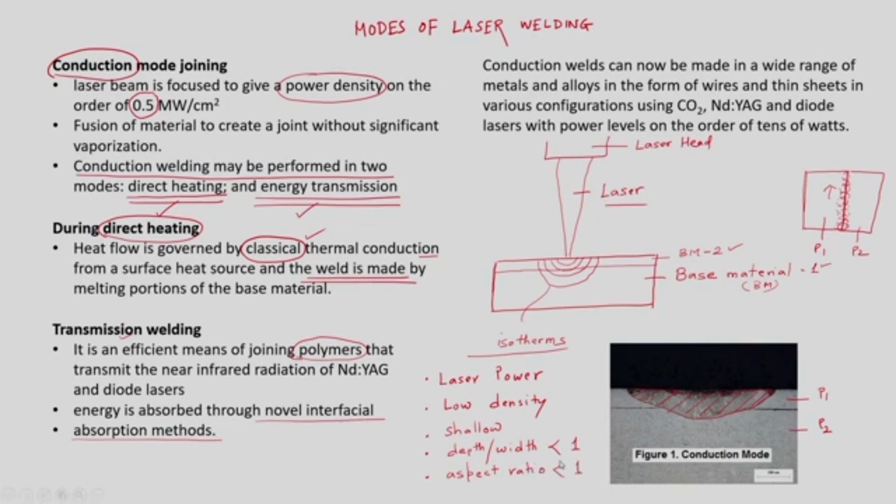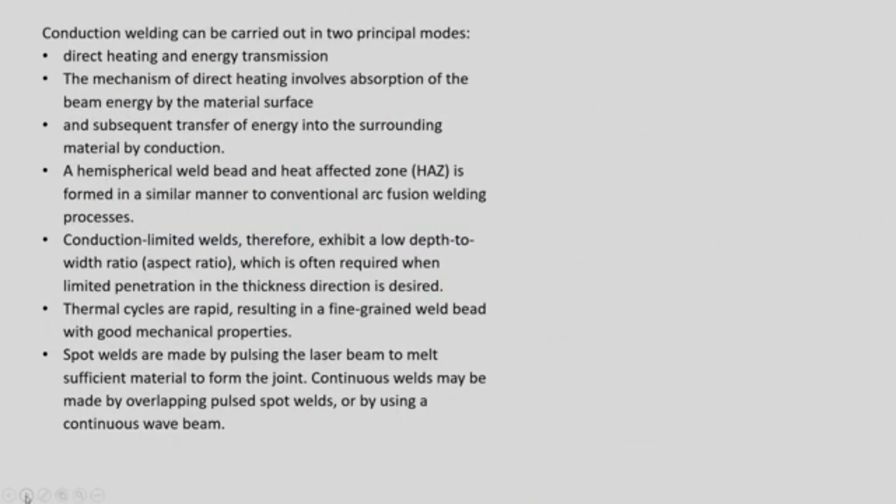So in conduction mode in particular, we are getting lower aspect ratios. So these are shallow and bowl shaped beads that are getting generated during the conduction mode. Fine, we have already seen about the direct heating and the energy transmission mechanism as well.